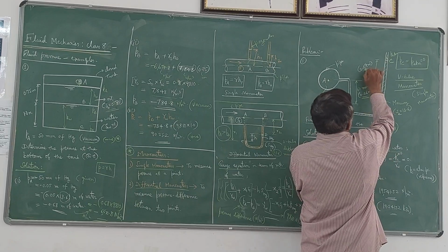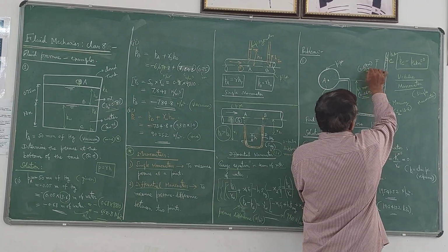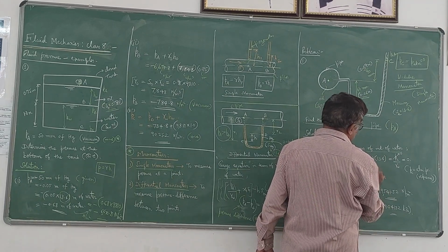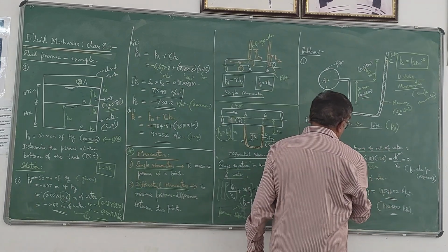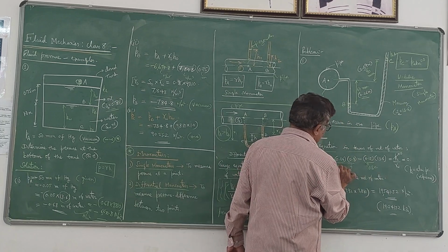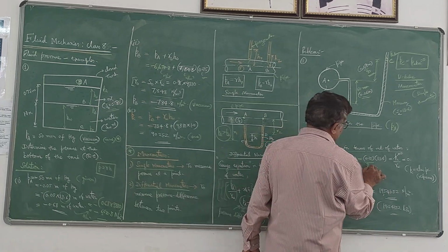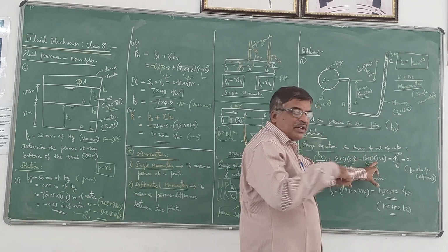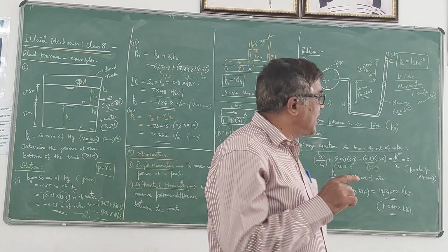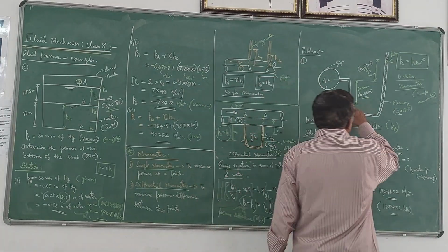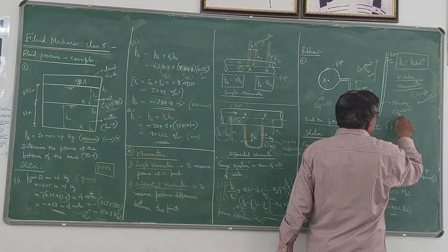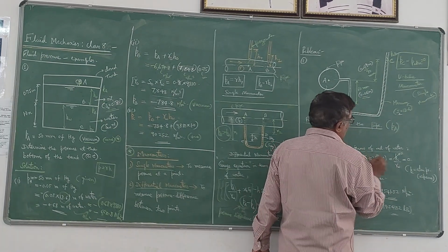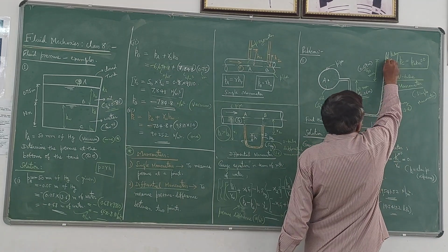I have to add these two now. When you add 0.06 and 0.09, you are getting 0.15. So this is the distance between B and C. Okay. Here we have to take the distance in meters into specific gravity of the liquid which is contained between those 2 points. So between these 2 points, mercury is there. Its specific gravity is 13.6. So into 13.6. This should be equal to, now we have come to the end point C.